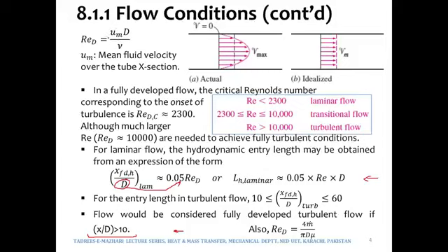So if we write this velocity as mass flow rate over density times area, we will come up with this expression. It's a couple of step procedure, you can do it by yourself. And since we would have area, it would be pi by 4 d square. That is why we are having a pi by 4 over here as well.